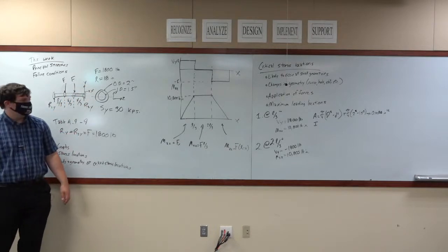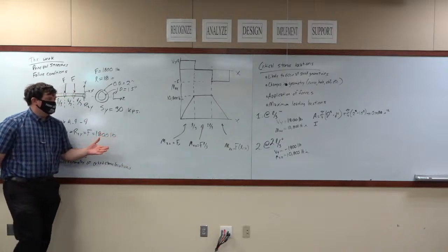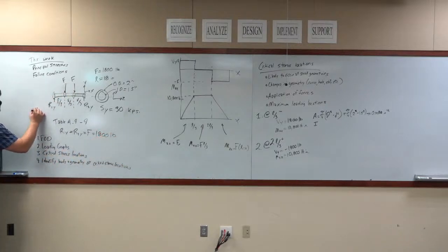But ignore that. If this was an I-beam in this configuration, it has a great amount of bending strength this way. You load the I-beam this way, in bending it, it doesn't bend very far. If you try to bend it in the other direction, loading it this way, where this is now the axis that it bends across, this actually bends a lot. This is a lot easier.